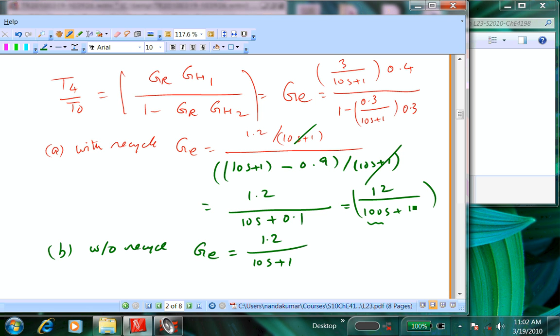So it is tau s plus 1. You need to have that 1 there, and then only the tau gets the meaning of the time constant. Because when you invert it, you will get e to the power minus t over tau. Right. So you need to rescale this. You cannot just leave it like that and say my time constant is 10. It's not. You need to rescale it such that this coefficient becomes 1, and then this gets the interpretation that it is a true time constant for a first-order process.